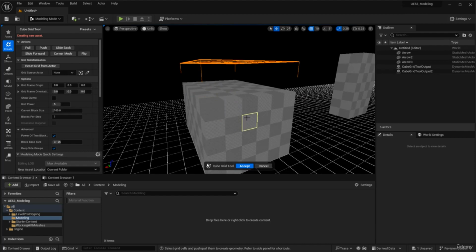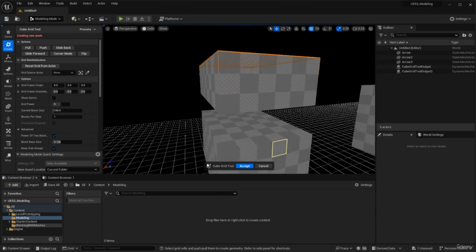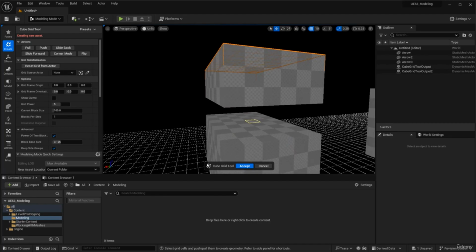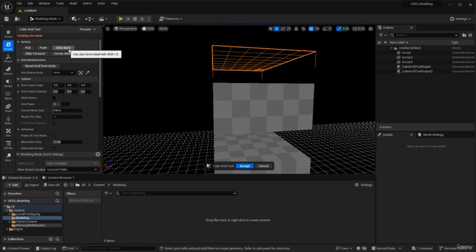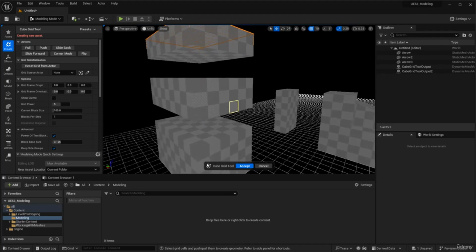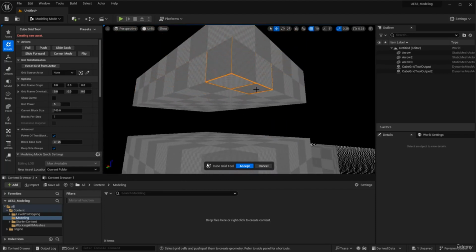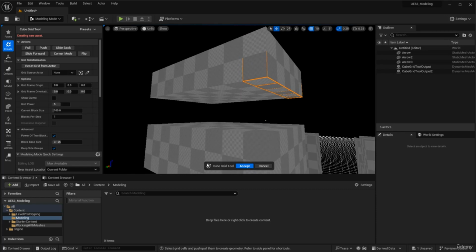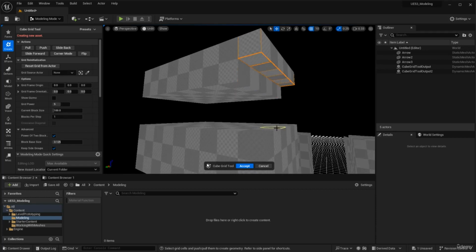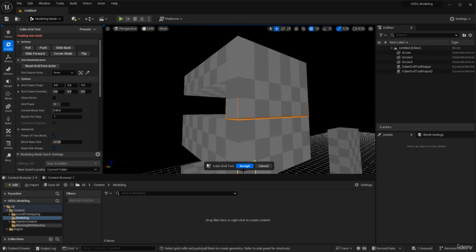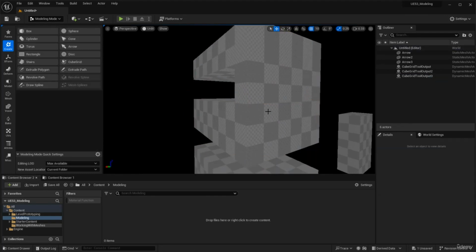And now if I hit E, I can create another layer with gap between them. So again, slide and E, you can create a gap between them. And you can select this line. And now if I hit Q, will subtract the mesh. If I hit E, this will add geometries based on the normals. And now if I hit accept, this is one mesh.